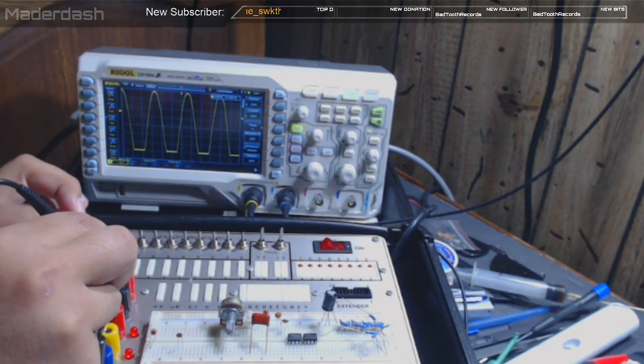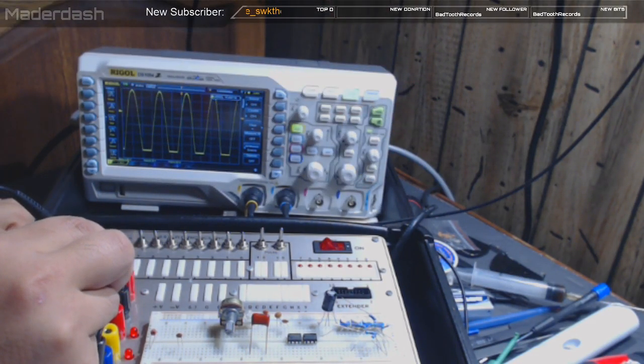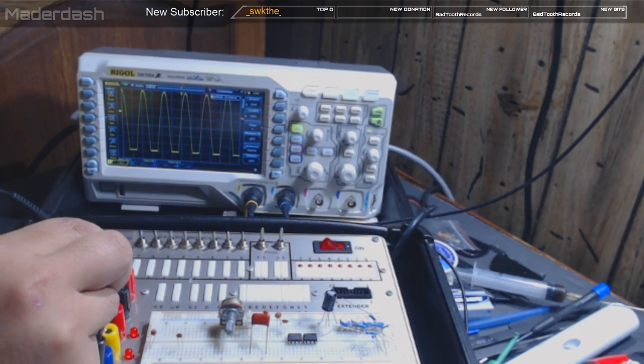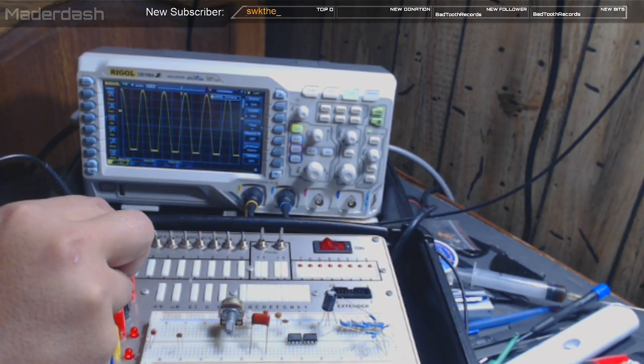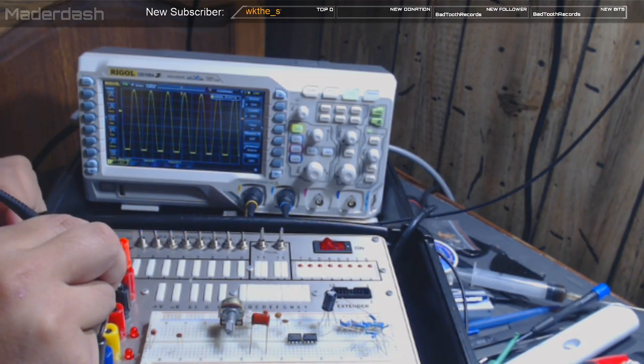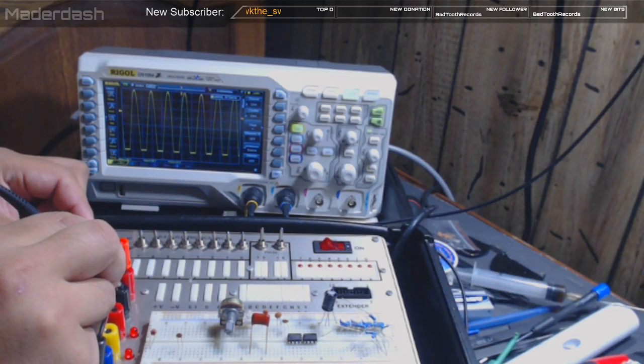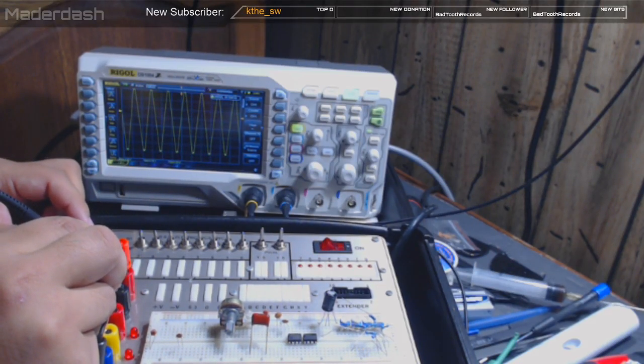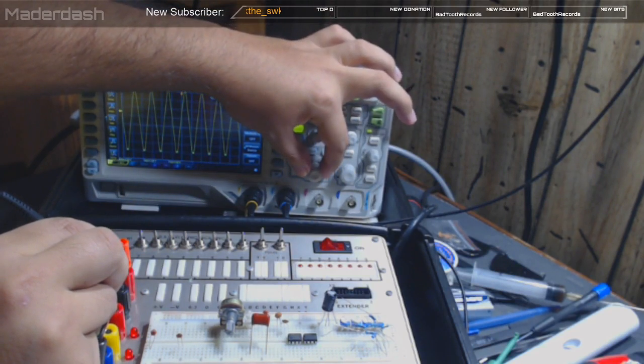Alright, so there's a generator, and you can adjust the frequency of it. It's clipping on the bottom, so obviously it needs some work. And you got a coarse and a fine, and then you can select, you see that's a sine wave, you can select a sawtooth wave. Let me adjust this a little bit.